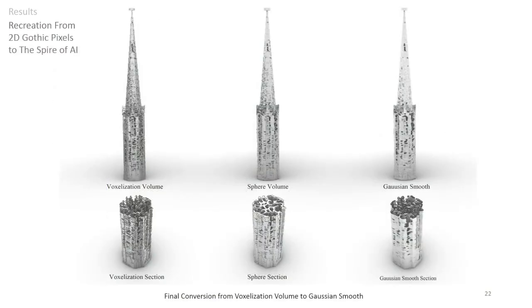The smoothing algorithm is then used with multiple values to replace the voxelization boxes with spherical surfaces. The additional Gaussian smoothing type and the number of smoothing iterations are all adjustable to transform the outcome into customized geometries with multiple design options.